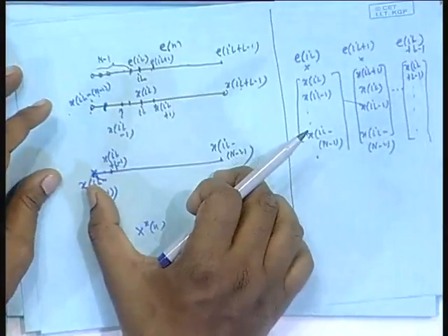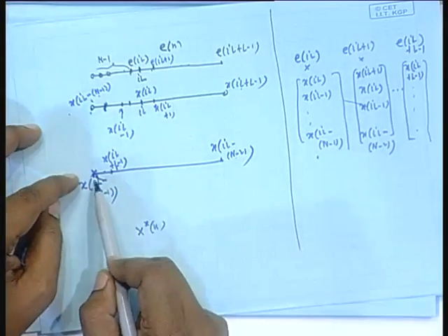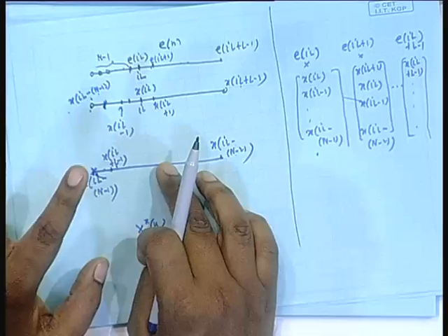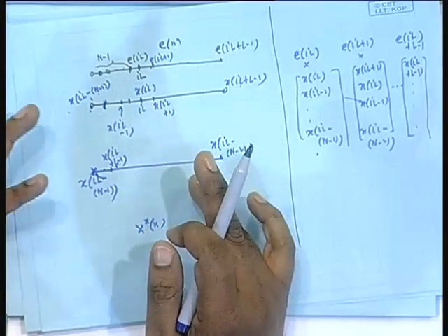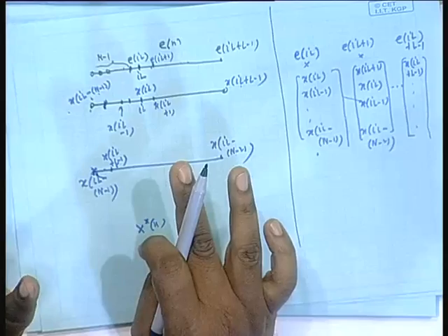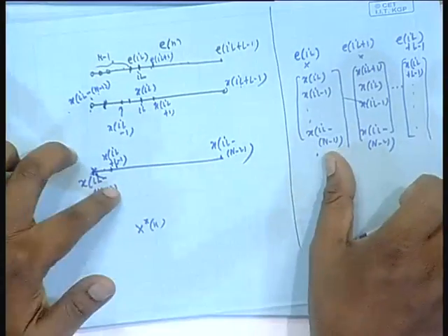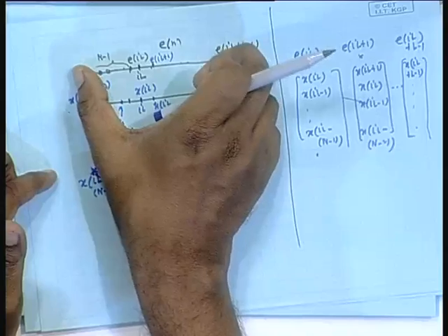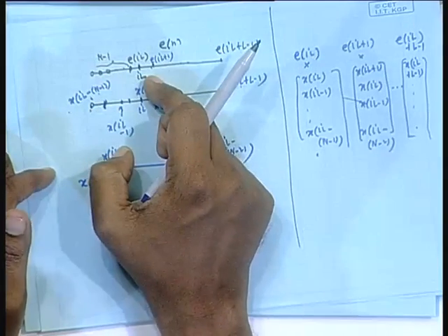DFT of this vector, which is flipped, except for the first element, everything is flipped, and assuming a conjugate, but there is no real data, so conjugate has no meaning. For that, if you take the DFT, it is nothing but x star k. So, I simply take x star k times, that is the circular convolution between this and this error sequence, which is 0 here.